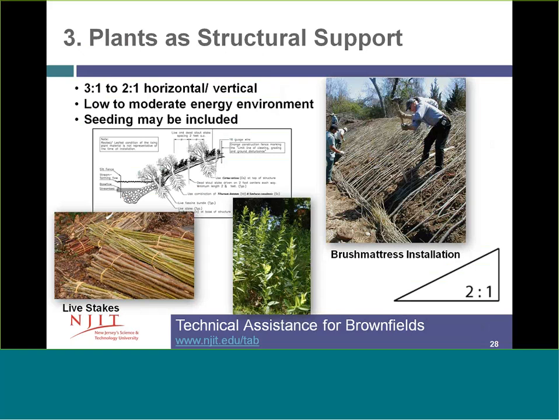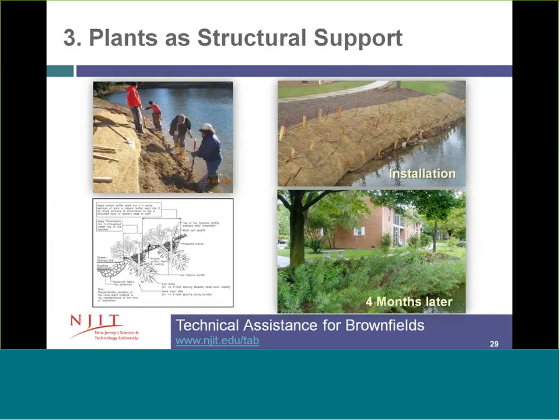On the upper right, you see a brush mattress installation. Those live stakes that you see are placed on the ground in the dormant condition. And the idea is that they provide actual physical support for the soils underneath, as well as a wave dissipator and energy dissipator. I'll get into that more in the next couple slides. You'll see on this slide a couple of different examples where we have live stakes and mattresses.